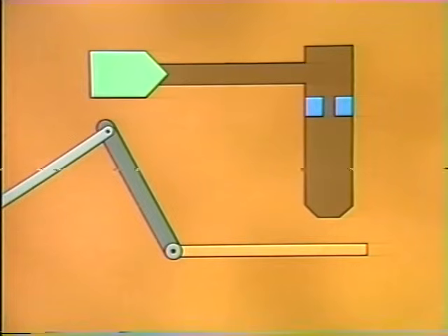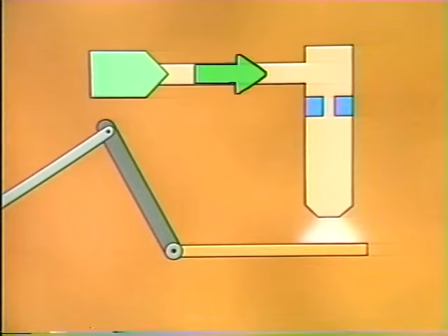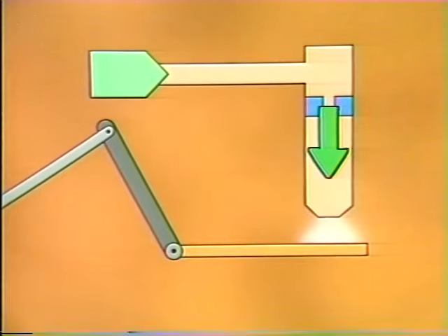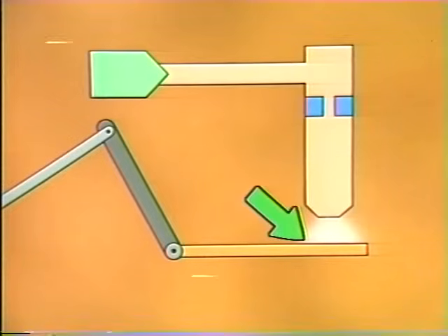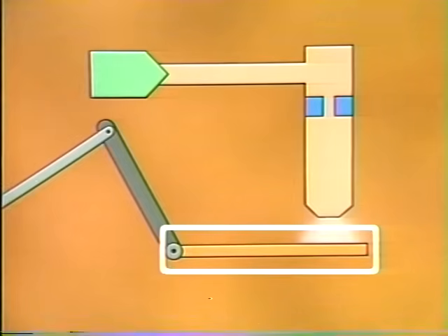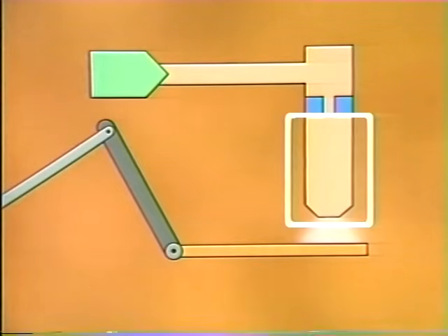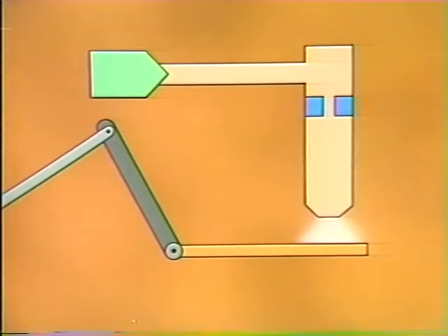Basically, the mechanism works like this. Instrument air flows through the restriction, through the nozzle, and is forced against the flapper. Where the input mechanism positions the flapper determines how much pressure develops in the back pressure compartment. Normally, this back pressure is the signal representing the condition of the process variable that goes to the output mechanism.